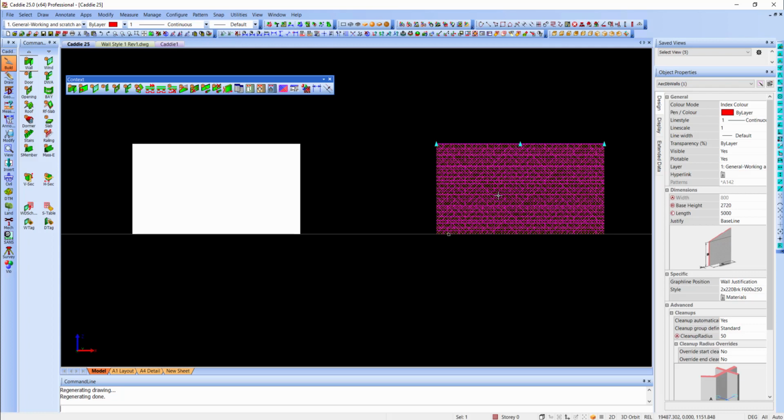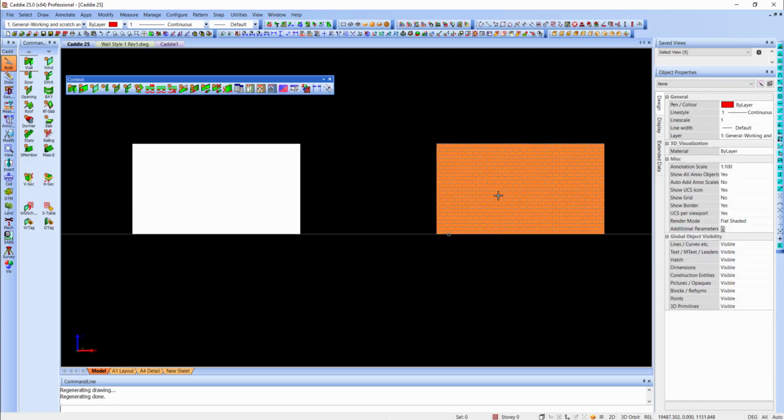Well, is this right? As you will surely tell me, this is wrong, as you cannot see it. Well, that does not mean it is not there. All this means is that it is just not displayed. The reason being is that the bottom of the walls are sitting on the 0 height level and the wall has a cut line also on that level.